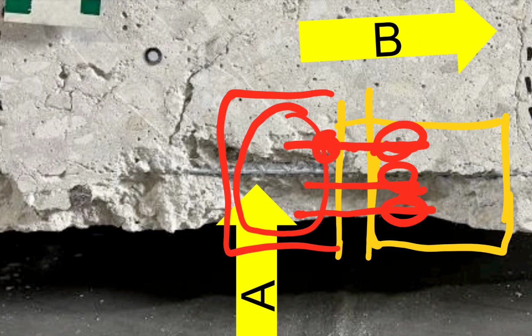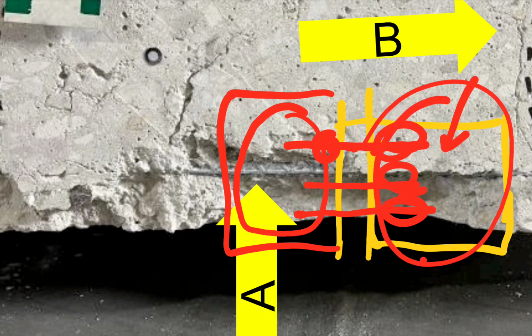So this will be determined through deflection monitoring, first that all floors are stable inside, with measurements, really low tech, but measurements and indicators that can be quickly monitored visually, not having to break out a tape measure again, stuff like that. It will be sacrificial indicators that would say, oh, we got movement here. In which case, you do propping and you adjust the floor. And maybe there's 2 floors in the whole building that will have to be done.